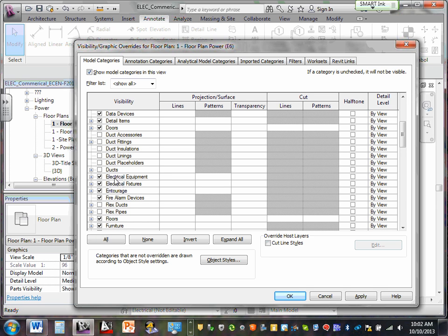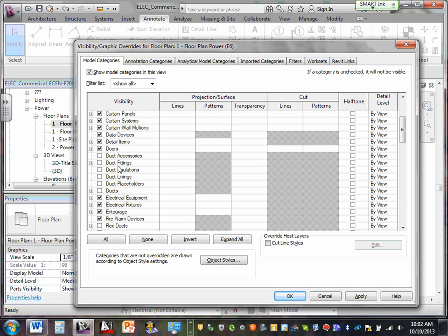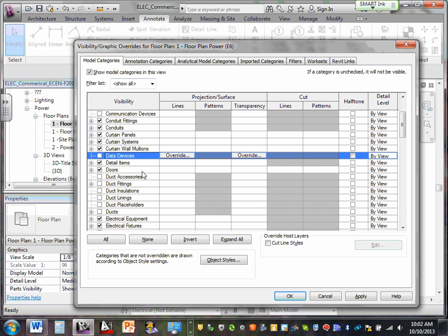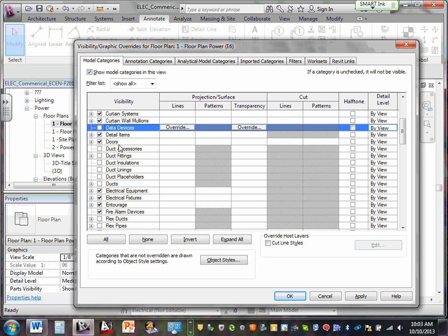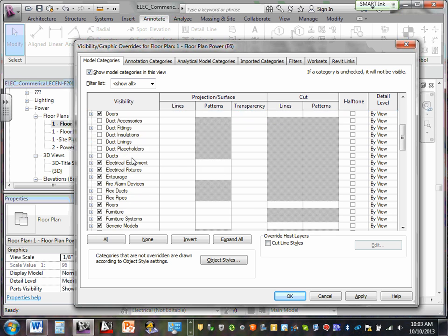Electrical. What is that? Oh, thank you. There's data devices. Thank you. Everybody can see what data devices. Unclick that one. By the way, if you left it, you will know about it when you start laying out. You'll see them there. You just come over here and turn them off. These are equivalent to turning off your layers or freezing them. Remember how we freeze? Actually, it's not turning them off. It's freezing them because it's freezing them in this view. Okay, so now data, freeze this. Turn them off. Okay. If I miss something, will you bring it to my attention?